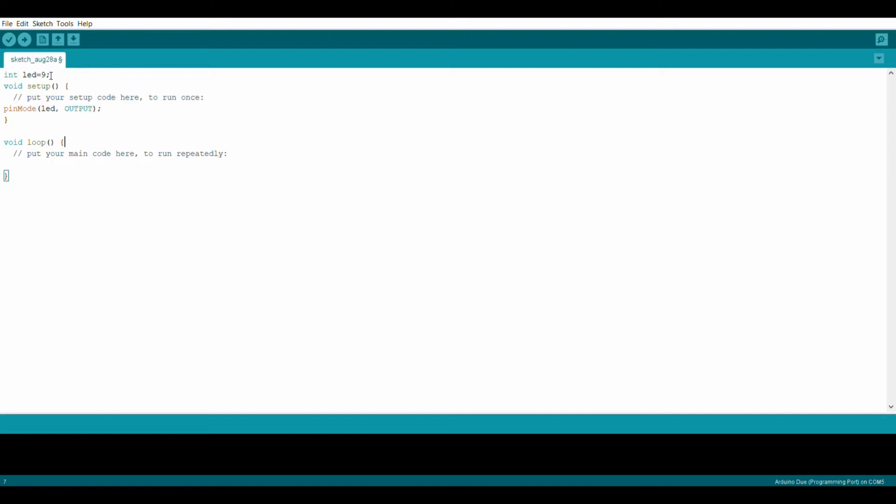Next, to light up the LED, connect its negative end to the ground denoted as GND in the digital array and the positive end to the pin we just declared, 9 here. Remember to use a resistor so that you wouldn't damage the LED. Next, to light up the bulb, type digitalWrite and inside parentheses, LED, HIGH. You can declare it inside any function since it doesn't need the board to be idle. Okay.